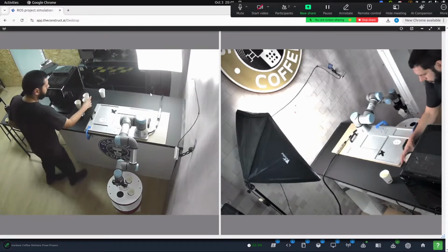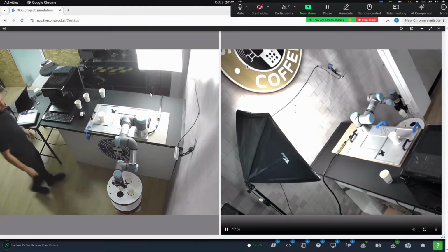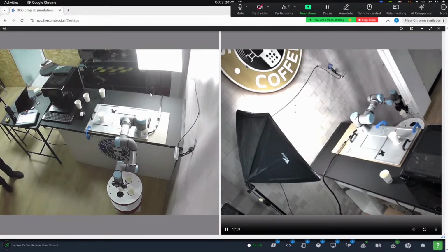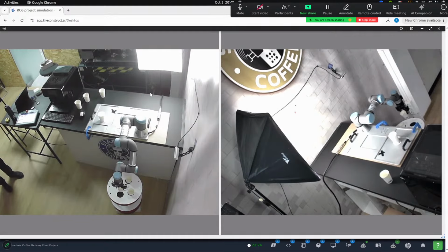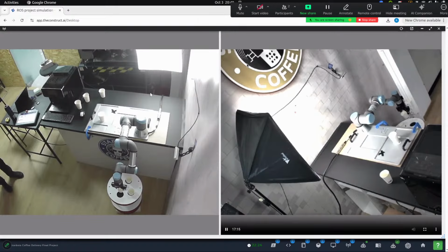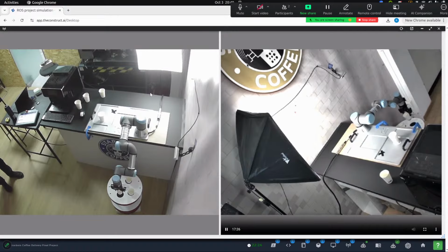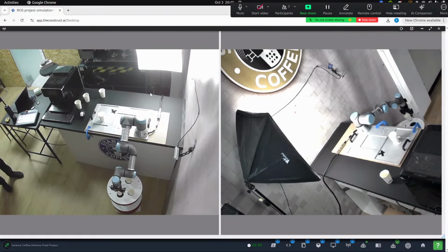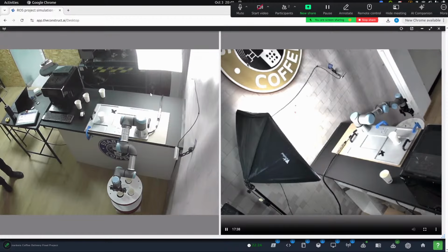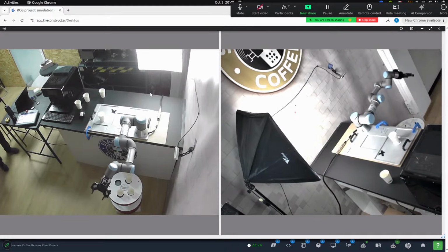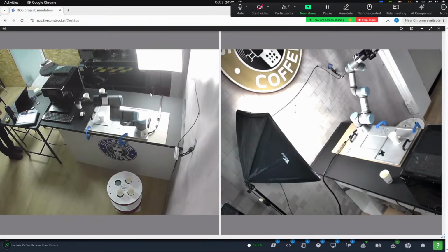So there it's moving slow. Maybe you can explain why it's doing that. Because it's out of the trajectory of the robot, you see it moves in small steps. The robot has joints, and it has limits, so it cannot reach beyond a certain point. These steps are done using a fraction. When the fraction is less than 0.9, compared to the first two, it wouldn't go as well. It would just go in very slow motion, because it cannot reach those points properly. This is the reason why it has to be constrained in order to do a proper motion in a particular region.